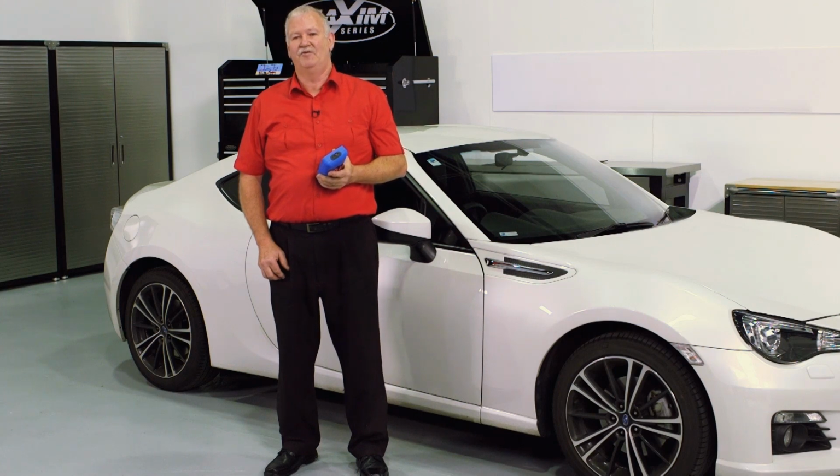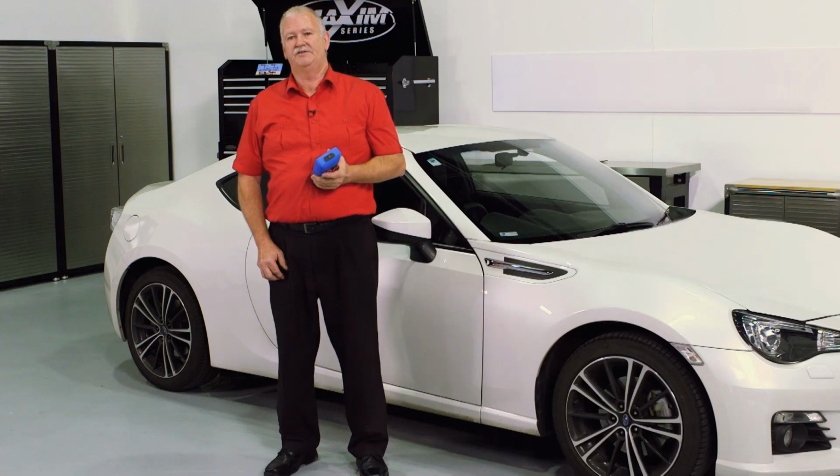These sensors are far more reliable, but regardless of which type of sensor is fitted to the vehicle, they're still tested all the same. If all the voltages are correct, it's probably the sensor. If one of the voltages is incorrect, that's our fault. And don't get yourself all tangled up. If you're looking for 5 volts and you see 4.5 volts, don't wonder why it's 4.5, just accept the fact that it's not 5 and go looking for the fault. This will help your diagnosis immensely.